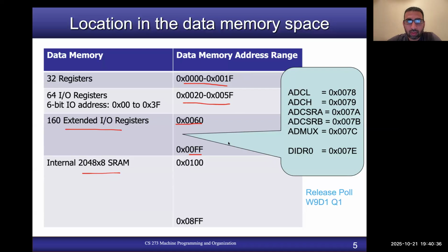Okay, I'm ending the poll here, and let me give you the answers. Depending on the packaging, Atmega328 has 6 or 8 input channels for ADC, and Atmega328 has a 10-bit ADC, right? And third question, Atmega328 has two external and one internal VREF sources, right? And ADC registers can be accessed using in or out. No, they cannot be. This statement is false.